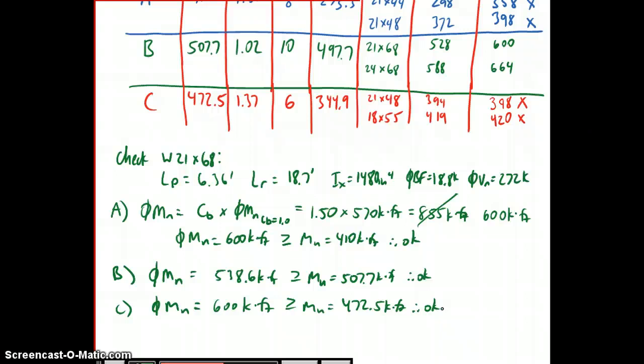That won't give us the actual value of moment due to self-weight because when we superimpose that wL squared over 8 on top of the max moment in segment B, the problem is the max moment in segment B isn't exactly in the middle of the beam. So we're superimposing two values of max moment, one from loads, one from self-weight. Problem is they're not actually occurring at the same point in the beam. That's okay for our purposes.